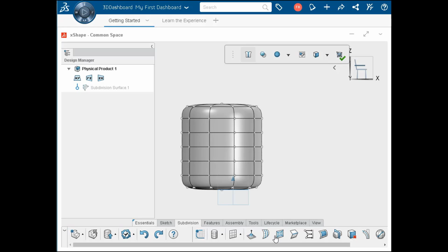To do this, we'll be using the Subdivide Faces tool. This is one of several tools that exist in two places, on the Action toolbar and on the Context menu. So let's talk about the differences for a moment. The Context menu is for single uses. When you create a crease, align, extrude, or subdivide the current selection, and then finish. The Action Bar version is better suited for multiple selections, adjustments, and continued use. We'll use the Action Bar version here to select and adjust two faces simultaneously.